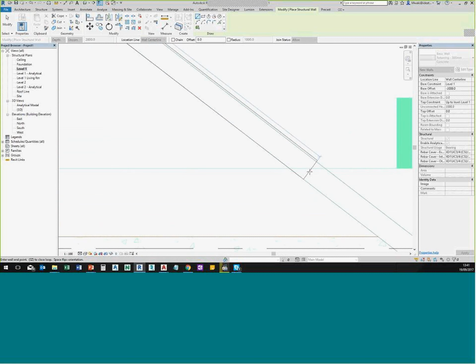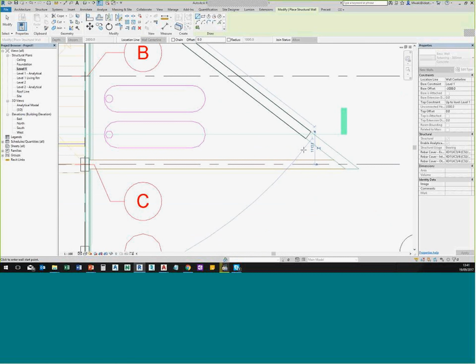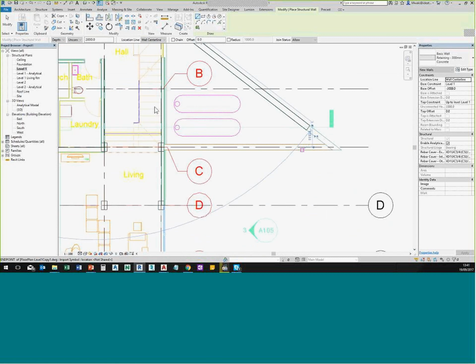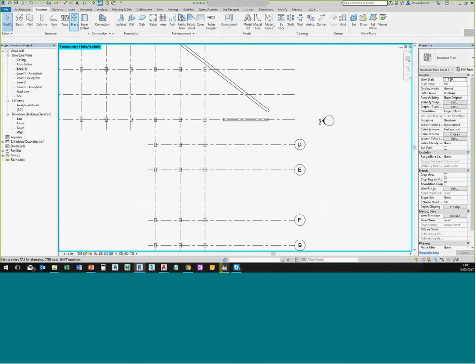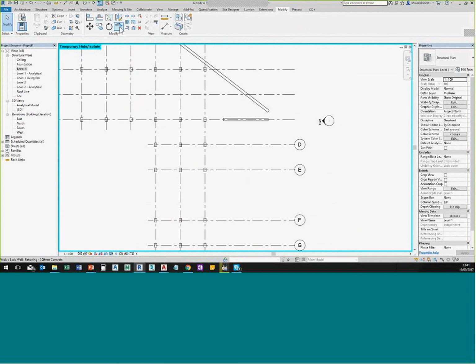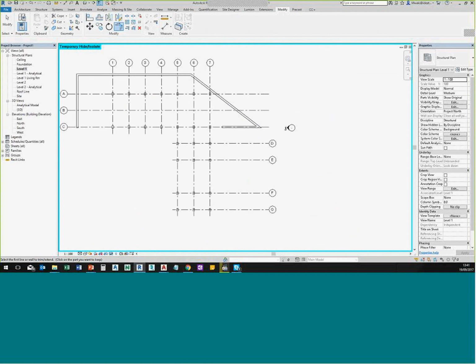What I can do is bring my wall just up to a point where I'm pretty confident I've got it correctly, and bring the other wall that way. Then I'll trim them to join. So for purposes of clarity, I'll just temporarily hide the DWG. In this case, H is my shortcut. So that's the actual model that we have. And I'll go ahead and go to the modify panel and use trim to trim.